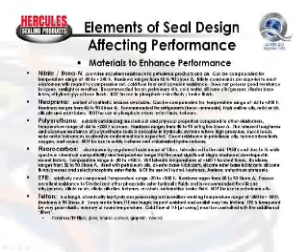One of the problems with Teflon is what's called cold flow or creep. We think in terms of an elastomeric seal like nitrile or urethane, we would call this extrusion. But when talking about Teflon, they call it cold flow or creep. And that is the characteristic of the seal material to flow under pressure between the two metal gaps of the cylinder.